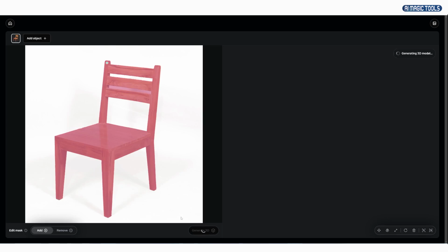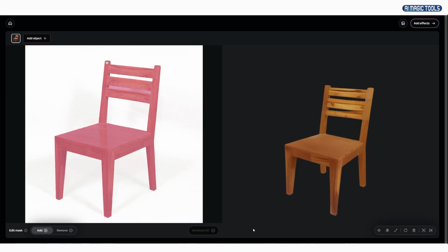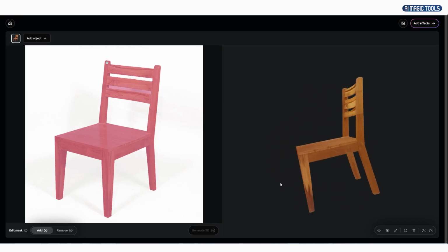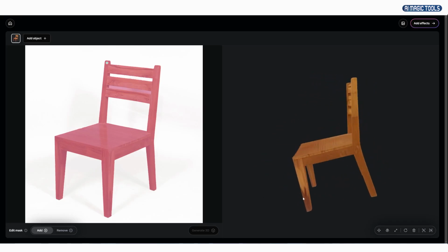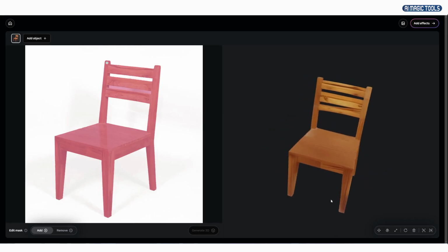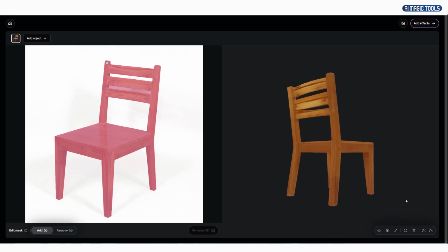Once you've got your shots, just dump them all into a folder named input_images. This is the moment of truth. With your images all ready to go, you run this one single command in your terminal. That's it. This one line kicks off the whole shebang. The AI segments the object, predicts its depth, aligns all the different views, and builds that final 3D mesh. This is where the magic happens.